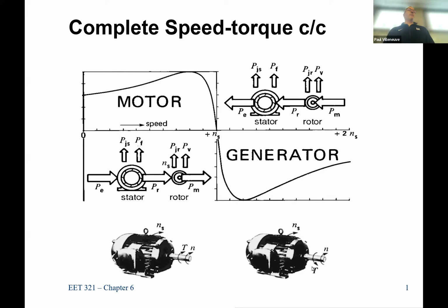Over here, the torque is in the opposite direction. Does that make any sense? It's a generator, but does that make sense that the torque's in the opposite direction? Think so? Would it be decelerating? Well, keep in mind, we want this to keep generating power. So what decelerates is whatever is driving the machine. So it could decelerate, but it's decelerating whatever's driving the machine. Is the electrical field moving the other way, giving it a resistance to push up against, and that's what's giving it torque? It's not really the electric field going the opposite direction, but you're absolutely right.